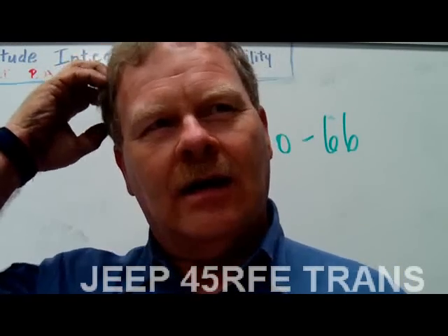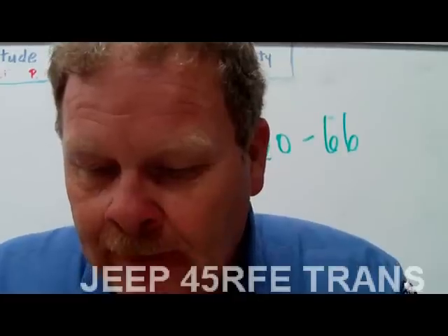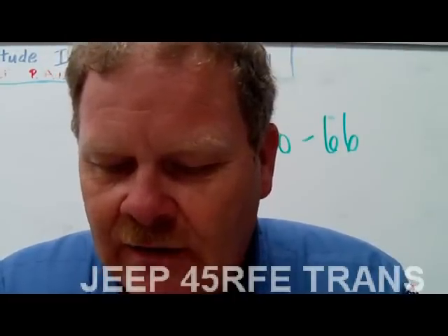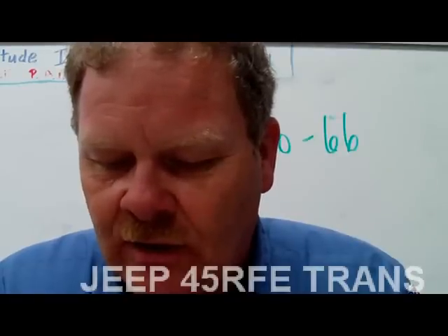We just got the answer to one of them. I think we got the answer to one. There you go. It's only used for passing gear. All right, and then you got 1 to 1 for third gear, obviously, and then you got your overdrive gear, which is 0.75 to 1.